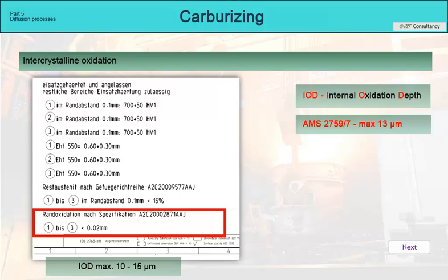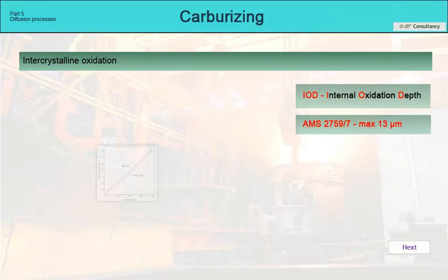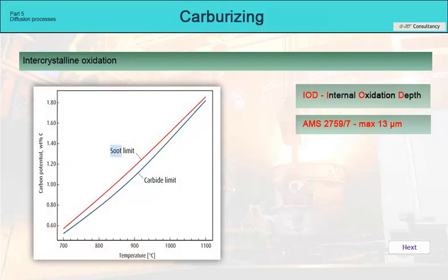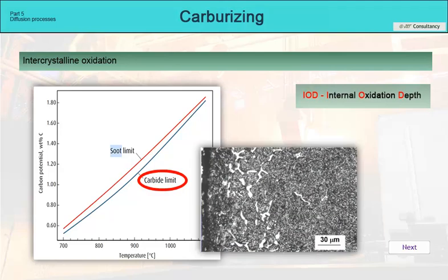If we oversaturate the steel surface so that we also exceed the solubility of carbon in austenite, another undesirable phenomenon will occur. Secondary cementite formations will begin to form. This phenomenon can occur especially when the surface is oversaturated and at the same time the steel is slowly cooled from the carburizing temperature to the quenching temperature.